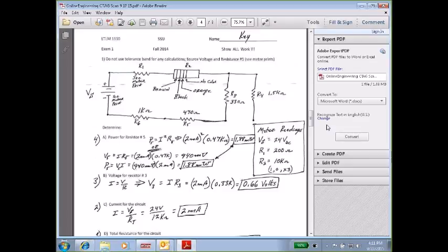If, for R3, we would take a piece of wire and just couple it in parallel with R3, then R3 would be shorted. In other words, we have a shorter path with less resistance rather than going through R3, because current is like we are, it's going to take the path of least resistance.